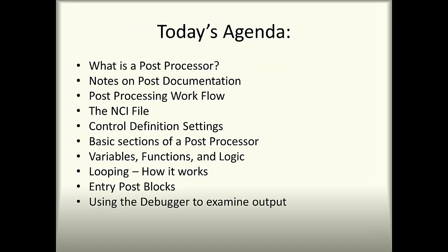Today's agenda: What is a post-processor? We're going to go over some notes on the post. We'll talk about the post-processing workflow, the NCI file, control definition settings of a post-processor, and then we'll look at variables, functions, and some logic inside a post. We'll talk about looping and how it works, discussion of entry post blocks, and we'll talk about using the debugger to examine post output.